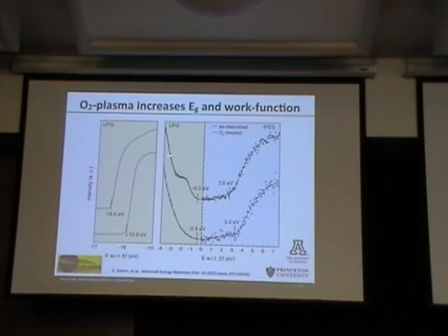Well, so that's why we turn to this spectroscopy. Now again, to be fair, here we've separated the two pieces out, so we're just looking at one component. But you see that when we do the nickel oxide, when we deposit it initially, you see the evidence for basically states near the gap that, when we oxygen plasma treat it, go away. Not only that, we see that the gap essentially widens a little bit.